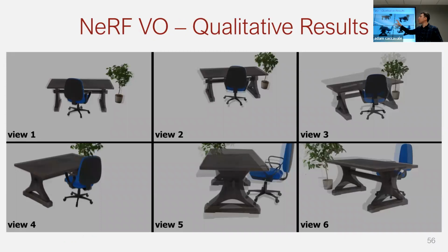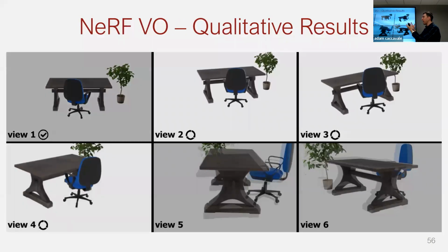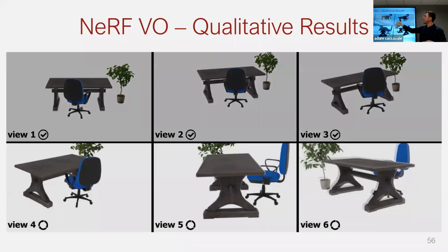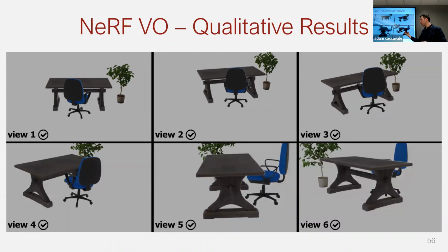These images here show the first 6 of the camera views. Right now you see both the measurement in transparent plus the robot's prediction of what it's going to see in solid. You can see that initially, there's a mismatch. As the sliding window progresses, you'll see the first 3 frames be optimized, they'll turn white, and the mismatch between the prediction and the measurement will correct. This window will increment and continue to increment. Once a view turns gray again, that means it's out of range of the sliding window, so there's no longer optimization being done on that camera pose. But if the object appears in the new views, that position will still be optimized as well. As you can see now at the end, everything that previously mismatched between the initial estimate and the measurement is now aligned.